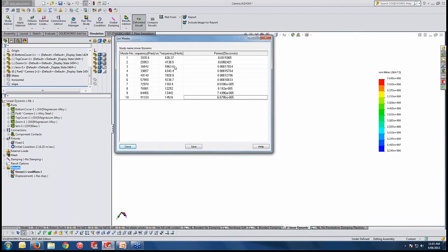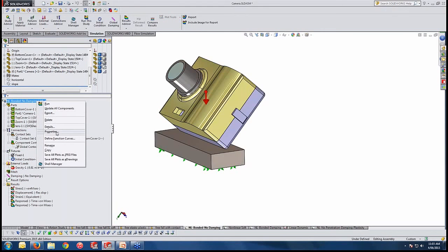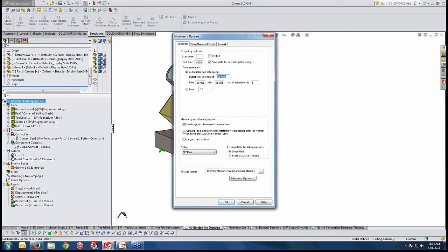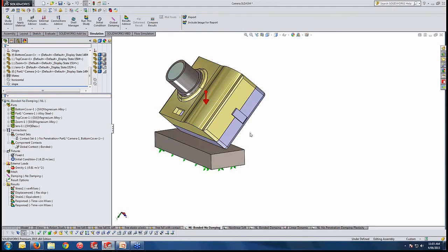Spending a lot of time, or a more relaxed approach, which is taking that time. So it is 1e minus 4, and what we have set up is no damping here. You can see I have put a very tiny time step to create the stress on the model, and just recording 5e minus 5 on my system. The rest is about your advanced options, which is using the force control and other factors for eliminating singularities, your convergence tolerance, and maximum iterations if you like to set it. From this point, the nonlinear study is ready to perform.